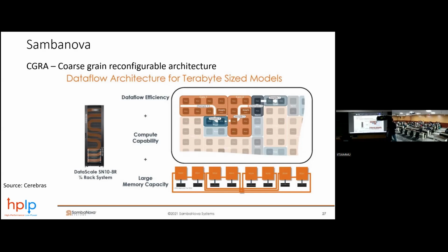Because these models and algorithms keep evolving, right? And if you build a chip that's hard-coded, an ASIC, when things change, it's kind of stuck. So you need to design the next chip. An FPGA allows you to build any hardware, but it's not very efficient because it's very fine-grained. You design everything with really small things, and it becomes much larger than an ASIC.